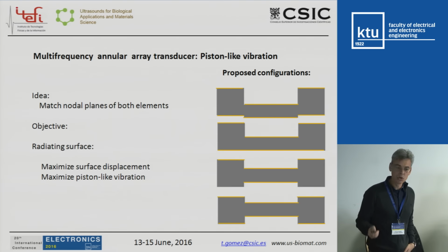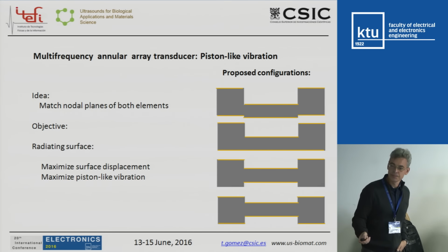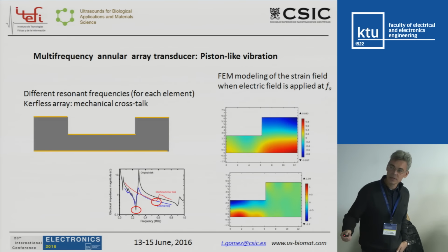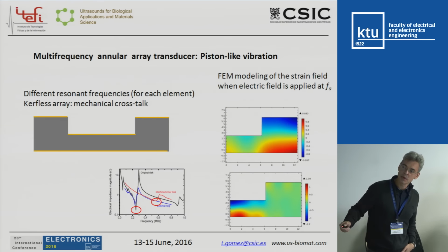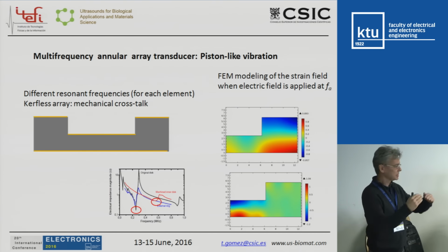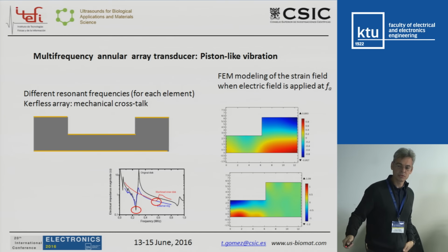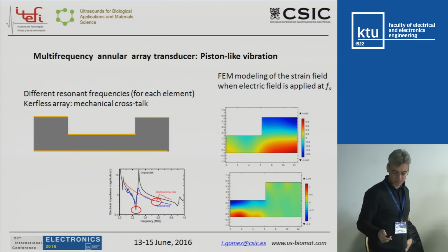Our proposal is, using this finite element modeling, the idea is: if we match the nodal planes, we have a nodal plane here, and we have a nodal plane here, but they are located at different heights. So the idea will be, if we match more or less these two nodal planes to the same location, probably we can improve the vibration here, and we don't disturb this much. So this is what we have done.